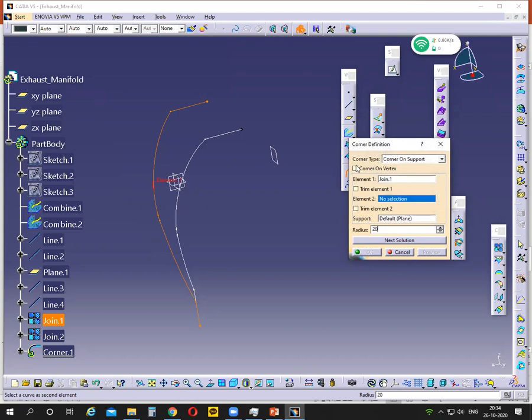So we have to select the corner and vertex option here. Okay, because we have 2 vertices here, right? One vertex is here and another vertex here. So here I want to give 20 and here. So corner and vertex. When you select corner and vertex, it automatically trims.